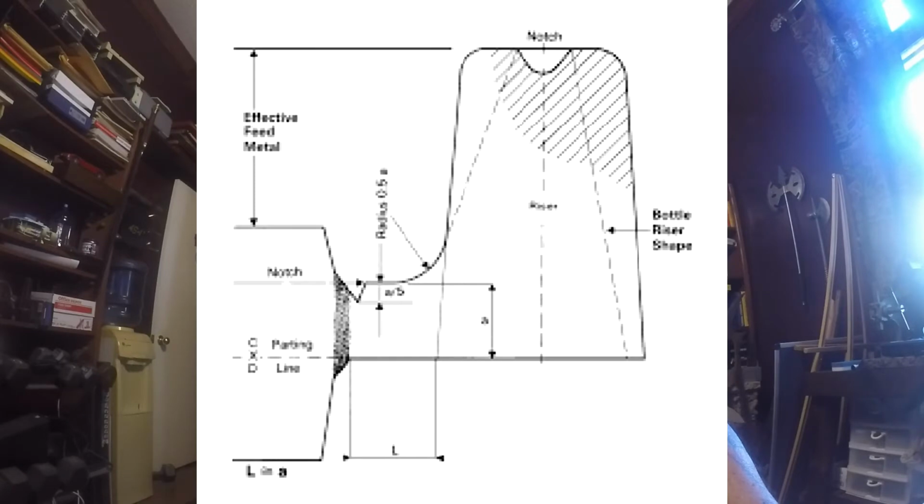In this case, the blind riser is close to the casting, to the side, and will still feed it very well. I don't like how small the contact area is there, because the neck right there in the middle of this is small enough that it might freeze up before the casting is fully fed, and before the molten metal in the riser has solidified.